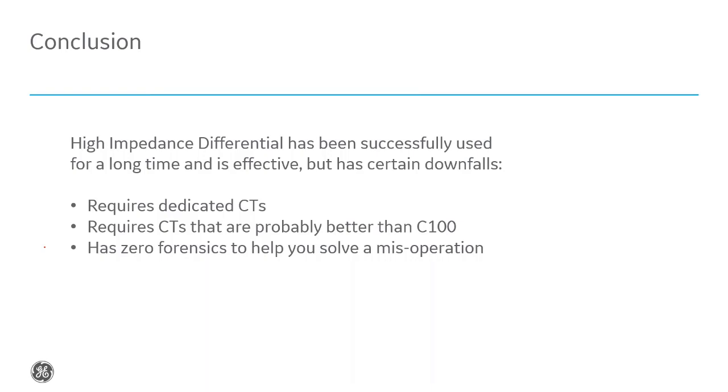Yeah. And the reason it did, obviously, was one of the CTs was wired backwards. Problem is they had no way to know how to find where the CT was, which CT was bad. So they had to spend a lot of time trying to figure that out.